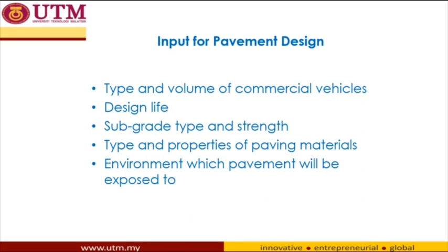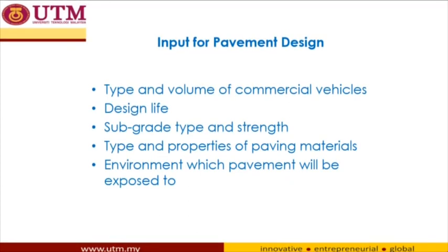Okay, next is the subgrade type and strength. So this is very important because subgrade is like our foundation for road construction. So we have to know the strength of the subgrade. For example, if the area has low subgrade strength, of course, we need to provide a greater thickness design.